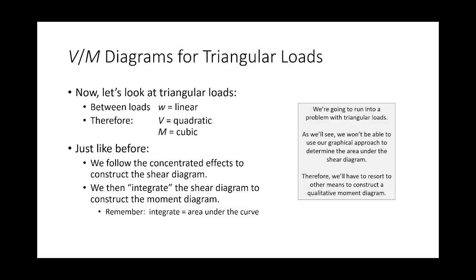So for triangular loads, it goes a step further. Our load diagram is linear, so that means our shear diagram is quadratic, and our moment diagram is cubic. And there's going to be a problem with triangular loads. There's going to be a little bit of a failure on the graphical approach, and the failure is this part right here, where we integrate the shear diagram to construct the moment diagram.